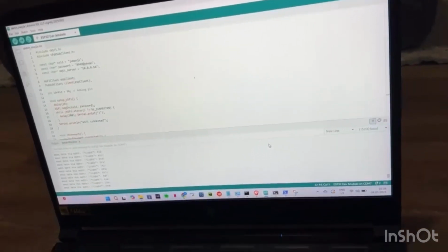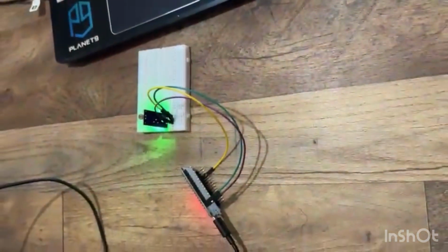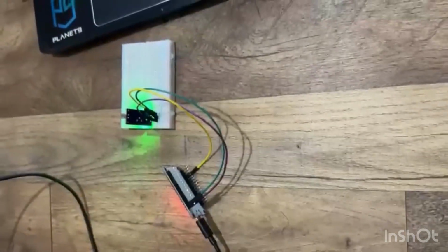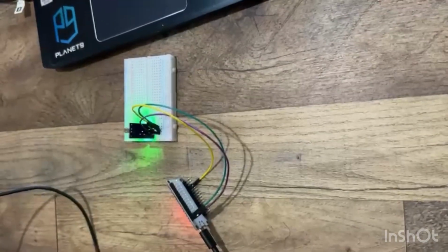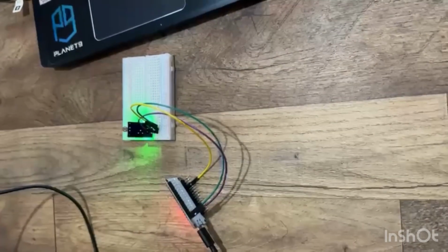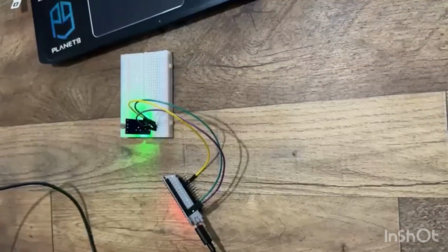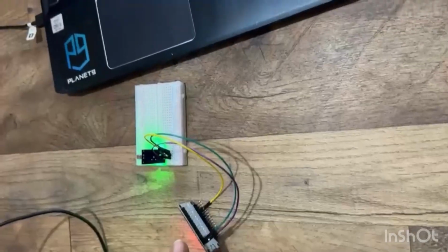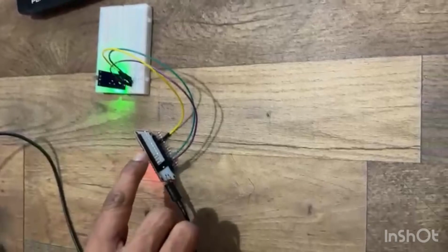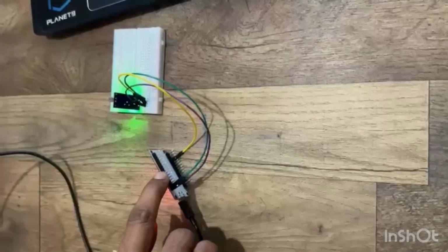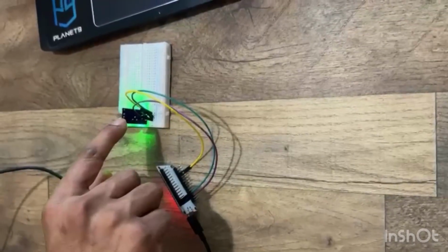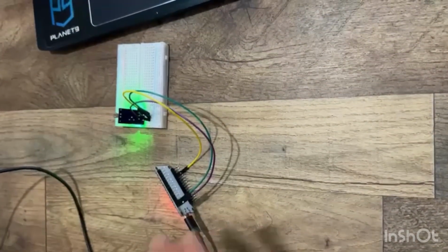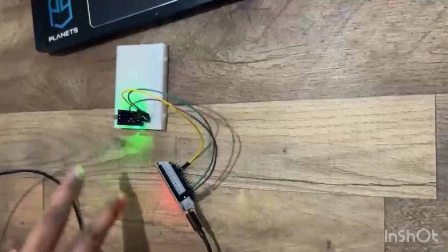So, the hardware we used and the components in the hardware we used are the ESP32 microcontroller. The reason we used this microcontroller is because it's low cost, obviously, Wi-Fi enabled, and very efficient for IoT projects. And the LDR sensor, this is the LDR sensor and this is the ESP32 microcontroller. So we are now on the LDR sensor. This is used to measure light intensity. Some basic resistor wiring for the circuit to connect the two devices.